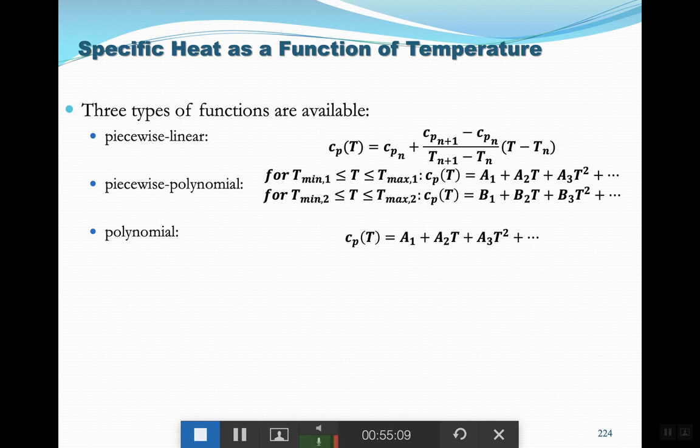So the point is, usually you use equations for density, for CP, for K, if for some specific reason you have the coefficients for it. Otherwise, using these functions would be a bit difficult, at points impossible, because essentially you don't know the coefficients, you don't know which one represents better. And remember, in CFD, if you don't have enough information, it is better to stick to the simpler models with predetermined coefficients, of which there is an abundance in Ansys.